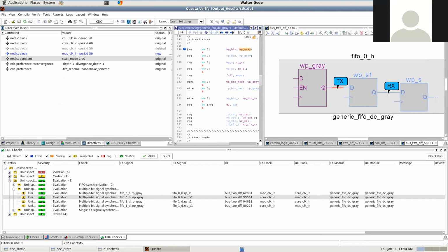And remember I said I can't do that, because there could be garbage, since these are flip-flops. But what it's telling me is that it's figured out that the data coming into here is gray-coded, so only one of these bits is going to change on any one clock cycle. So it's saying this is okay, because I've done the analysis that says this is gray-coded.